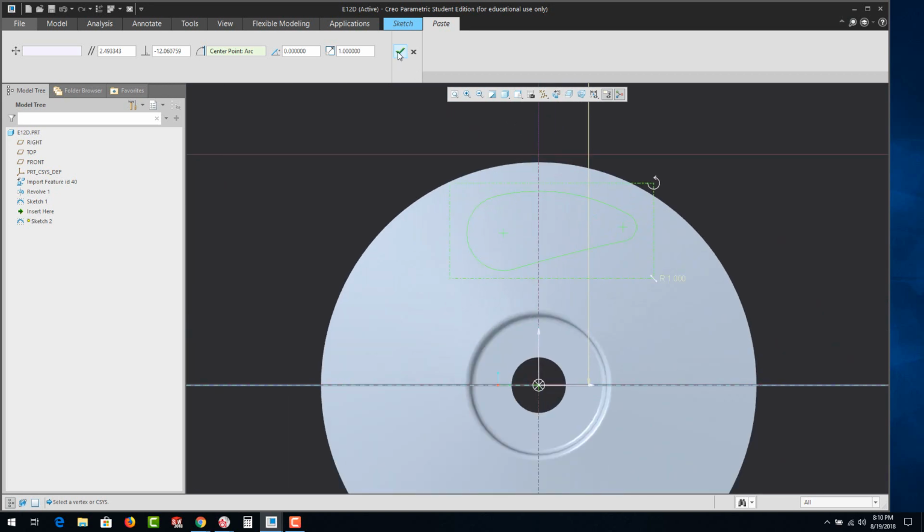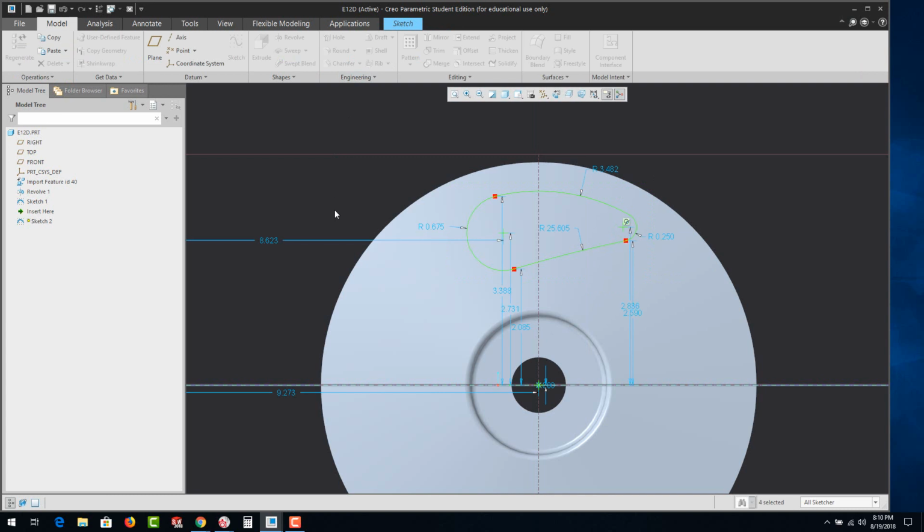We could go ahead and hit the green check mark here. However, it's interesting because in the past, with earlier versions, I've adjusted the actual precision very high, like to 7 decimal places at one point in an older version. I wasn't able to do that quite as easily here. I got it to 4 decimal places. And when I had it at very high precision, I would not get these little red markers, which means that there's gaps. So not sure why that is happening.